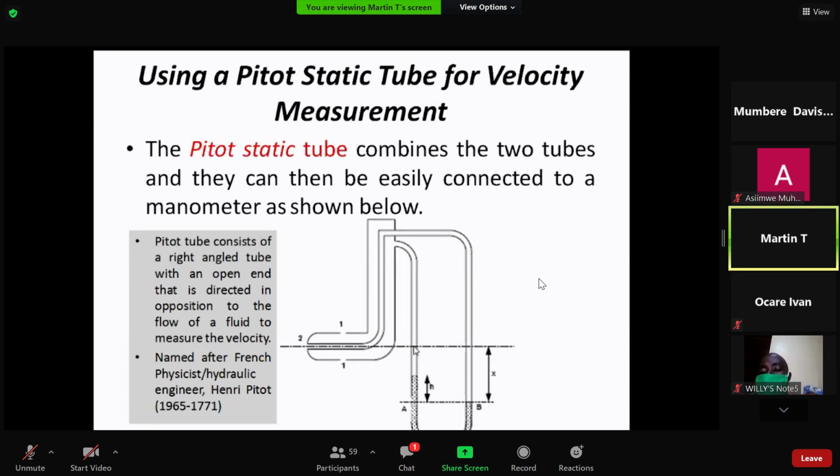So the other column of pressure exerted at point A is X minus H, rho g. Now, this rho is for which fluid? The one above, the flowing fluid. Yes, the fluid whose velocity we are determining, because the one that fills up this tube up to the separation with the manometric fluid.